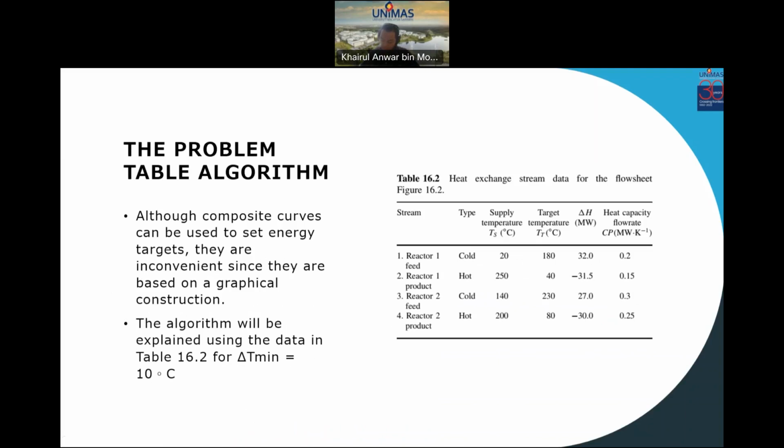This is referred to as data extraction. The problem table algorithm is another method to identify the pinch point. Last week we learned about the composite curve, the limited composite curve (LCC), using a graph. Now we use a numerical method to identify the pinch.